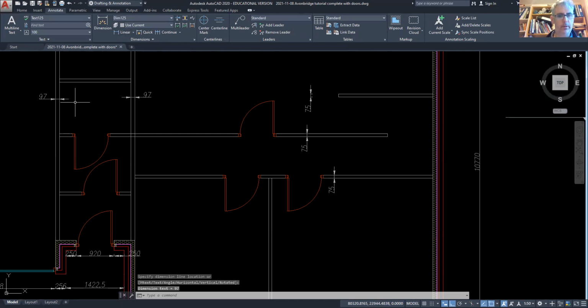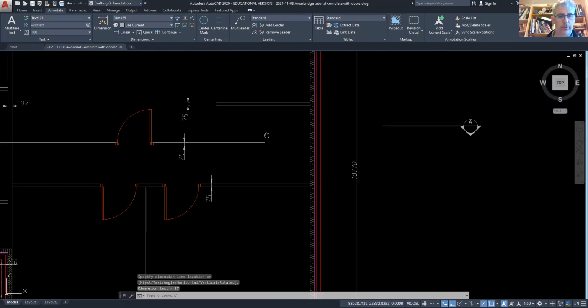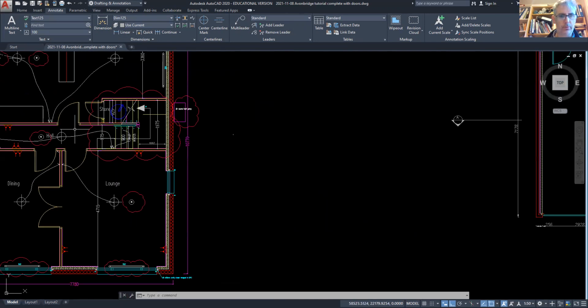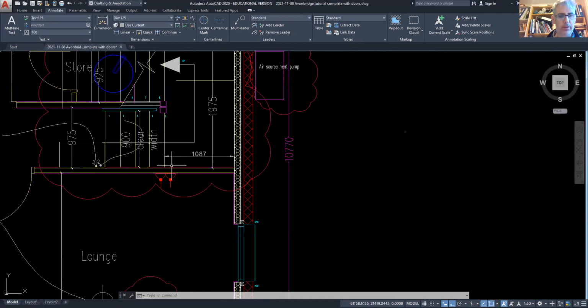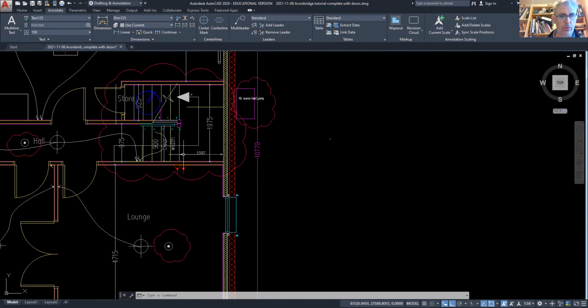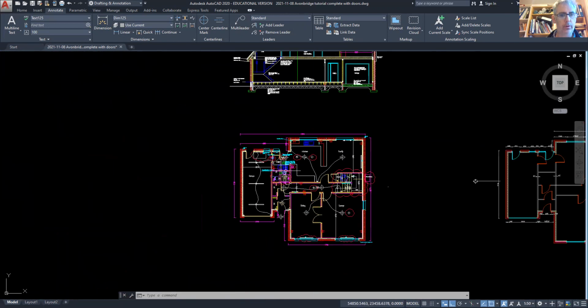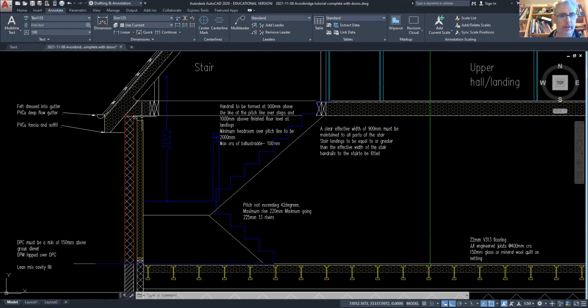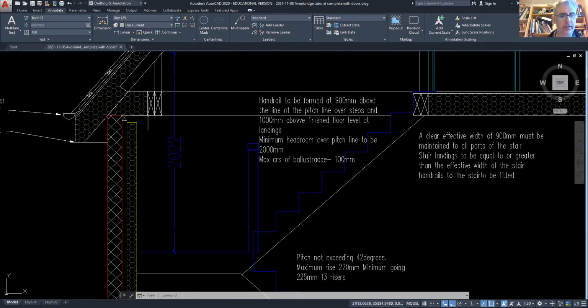there we go. Okay, so now we've got to put our stairs in here, and I'm just going to refer to the drawing that we did previously. We need this to be 1087, and the reason for that is because when you look at the side view, you will see that we need to have a certain dimension here, okay, because we've got some kind of ceiling, if you like, just at this point here. This is a soffit, basically the underside of this.